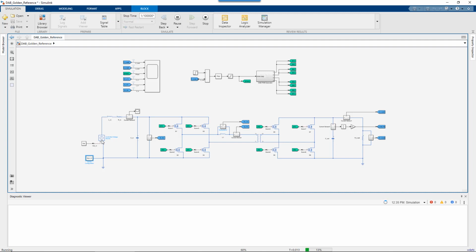So in MMC, you could have hundreds of PWM signals all triggering different zero crossings. And a fixed step solver doesn't care how many zero crossings there were. It's taking the same amount of steps no matter what. So the fewer transistors you have, the less likely a fixed step solver will help you. The more transistors you have, the more likely a fixed step solver will help you.